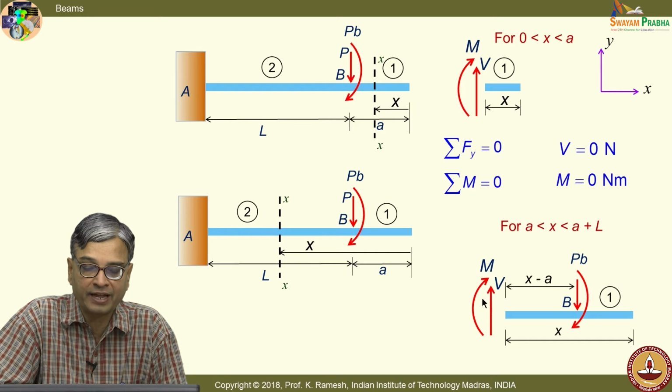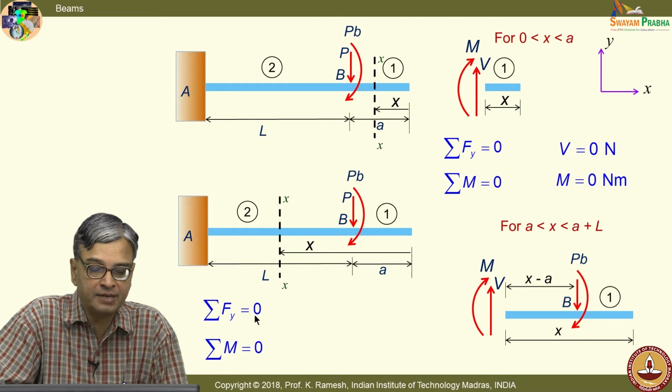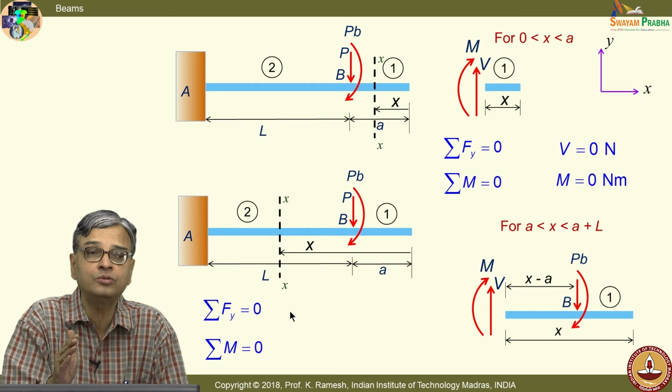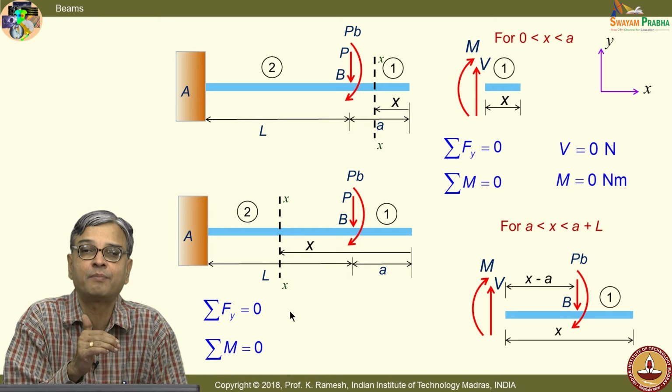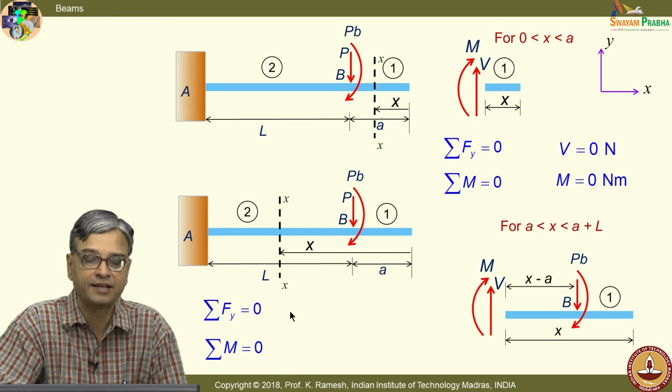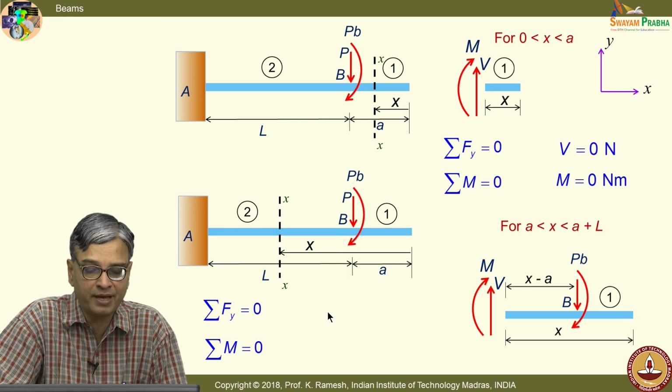So, when I recognize the sign for V, I will put that as positive, and I am missing that step. I am not writing the complete steps systematically. I am directly solving it and giving the values of Fy, but I would urge you to write the intermediate steps yourself and verify your answer with my final answer. If you do not do that, you may make mistakes later. So, when I use this equation, I get the shear force as simply P in this section.